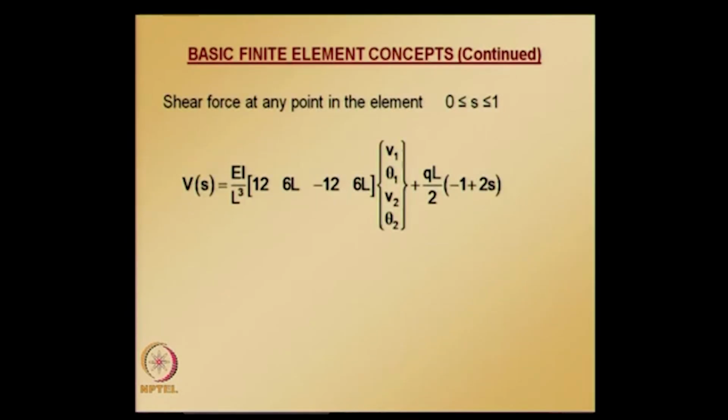The first term is nothing but interpolation of the nodal values as you do for any other problem with concentrated loads, and the second term is the correction term for the distributed load case.